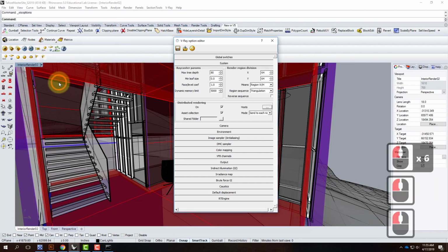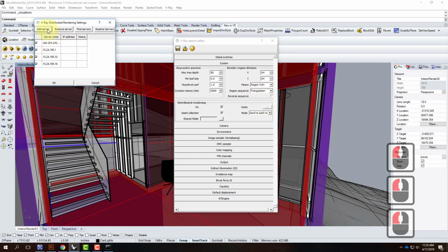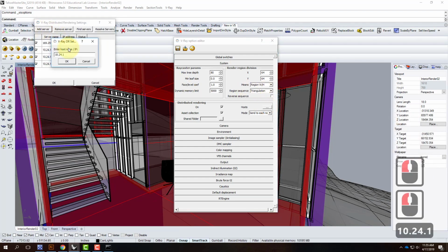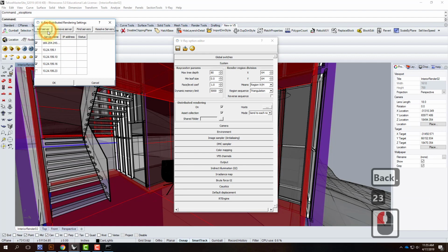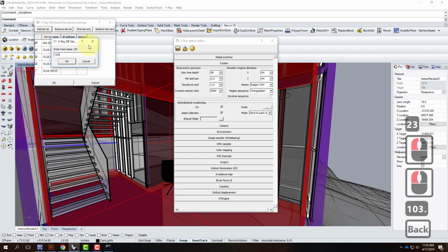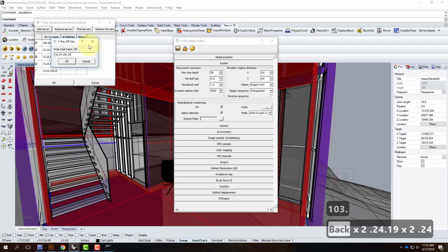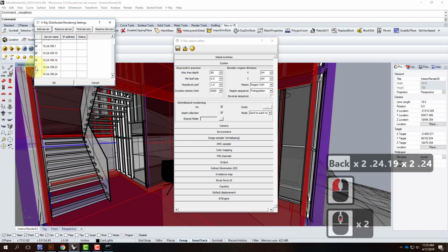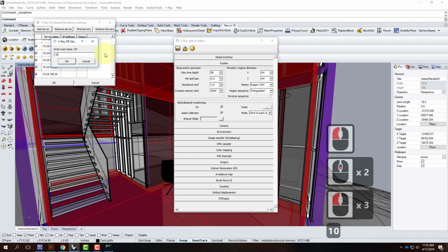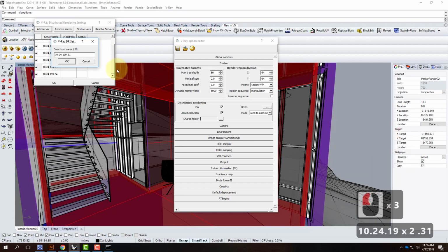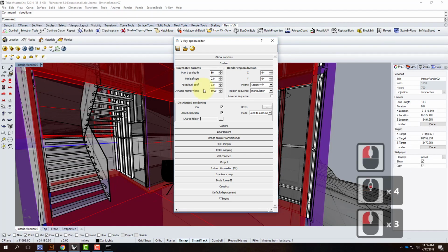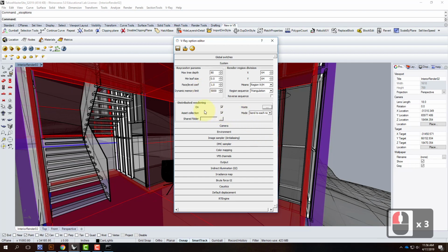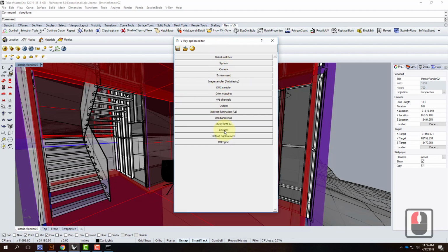Resolve those servers. I'm going to say OK. I added a small group. Then I'll come back and add a few more. Add server 10.24.199.23. OK. So I added a few more. We'll resolve those servers again. We'll say OK. And that time V-Ray didn't crash. That's good. So distributed rendering is on. That will speed up my render times. The rest of my settings are all good.